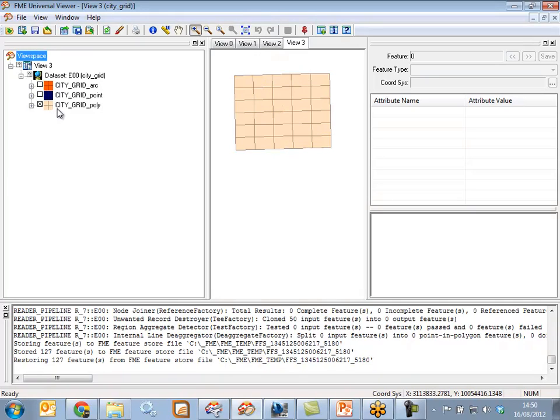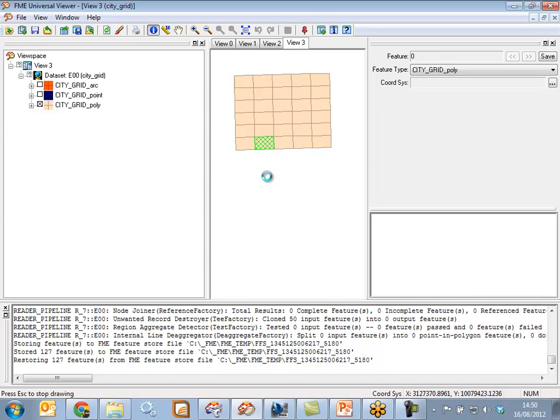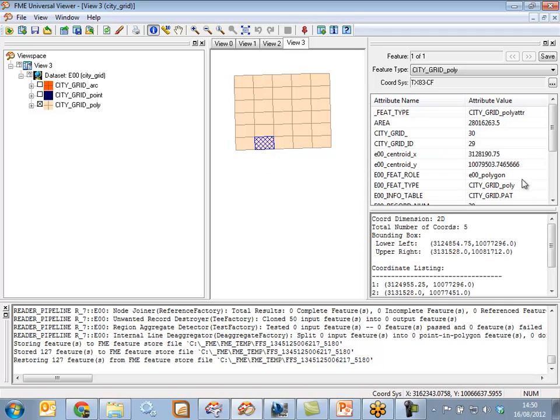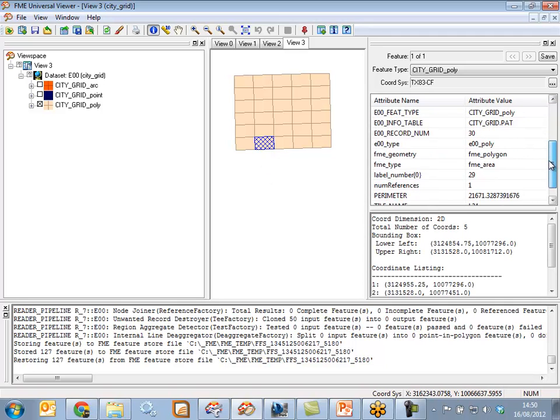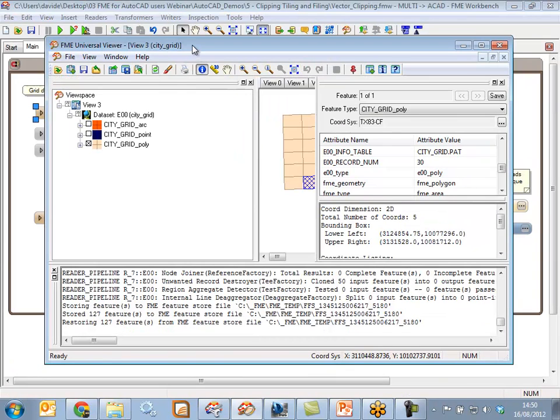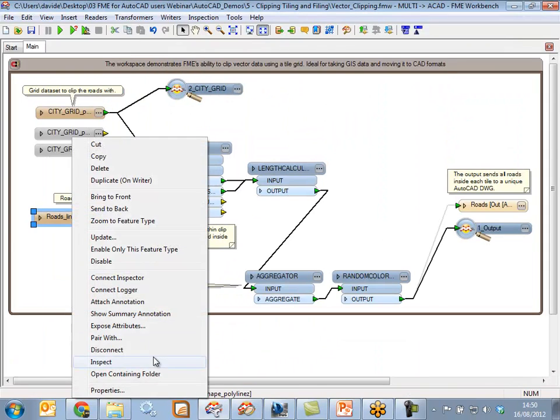Here there is one layer inside this city grid file, and this is an Esri exchange format. You can see that there are some polygons tucked away in here, and each one of these polygons has a value, and the value here is tile name. In this case L24 is the name that we're going to find useful.